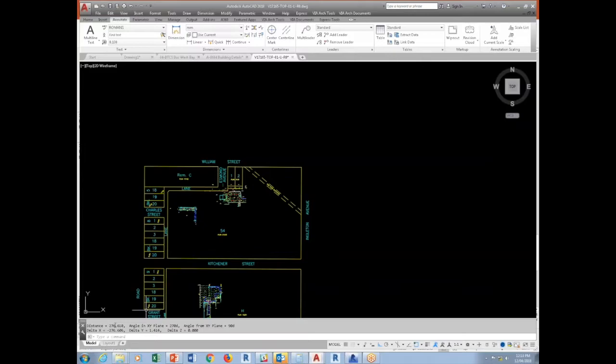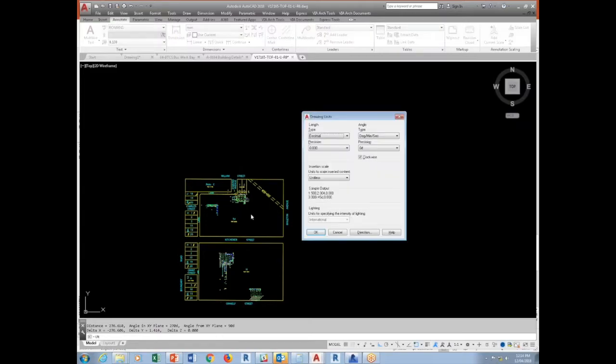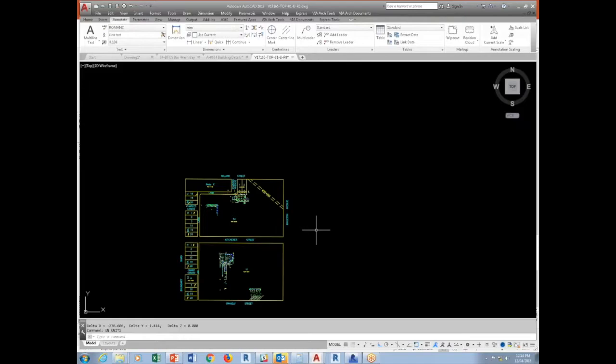Whenever you receive files from civil engineers, they always work in those two units. They're not going to be in millimeters. Don't ask them to translate that into feet, inches, or millimeters, because they won't do it for you. You have to make sure you understand. This one is already in meters, so I'm just going to set it to meters. That's the first important thing.